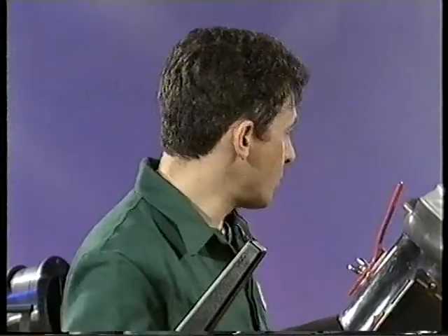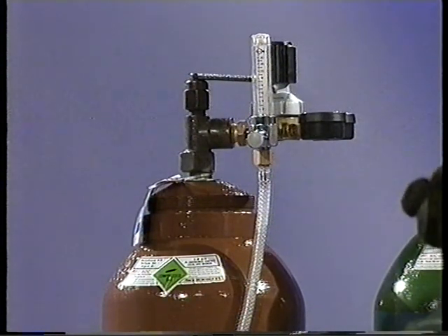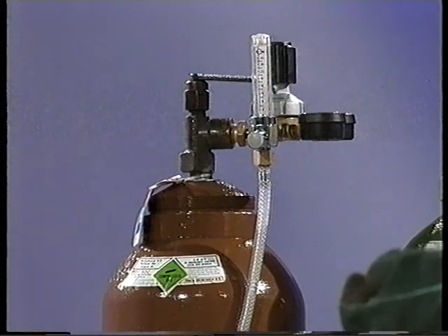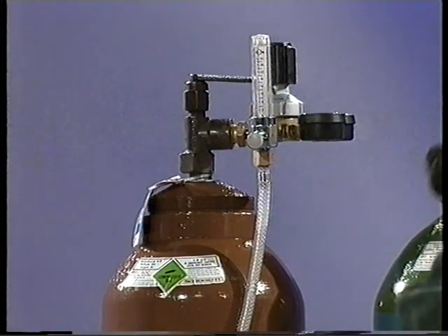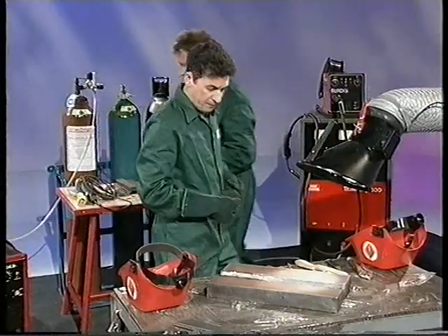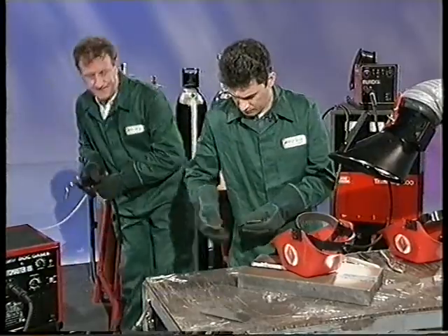Okay, well Rick, for that, have you changed the gas for this as well? Yeah, the previous gas mixtures that we've used have had active ingredients such as carbon dioxide or oxygen. In this case, we're going to be using an inert mixture of helium and argon. Okay, let's go for that then. Get some work on the bench ready. Turn the machine on.